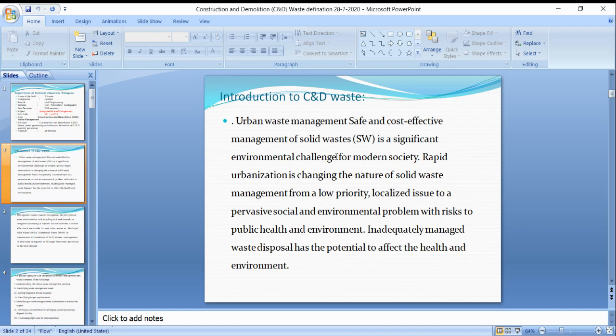We have already seen the common methods. For biomedical waste we will not go for the open pit method. Sanitary landfilling is useful for municipal solid waste disposal. For biomedical waste we use the microwave or autoclave method, or the incineration method. So these are the methods used for biomedical waste.